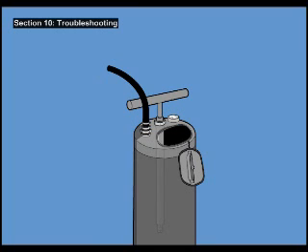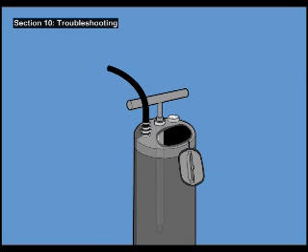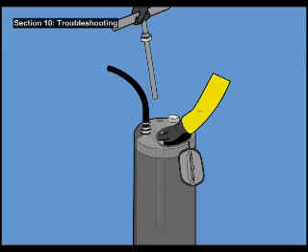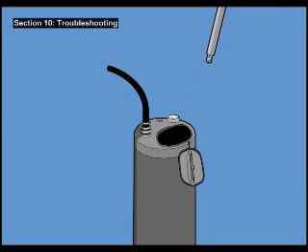remove the pump plunger from the sprayer by loosening the nut holding the pump on the top of the tank. Insert a gloved hand into the tank and hold the pump cylinder. Unscrew the cap holding the pump and pull the plunger from the tank. Remove the pump cylinder from inside the tank.